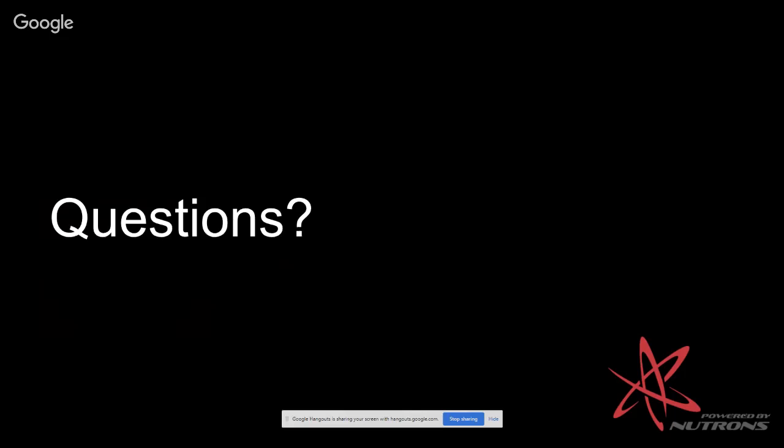So almost every single team will use some sort of gyro feedback in their code, because if you don't, you'll just drift off, and if you don't use encoders, you won't drive the same amount every time. So sensors become a very important part for repeatability of your autonomous routines. For teleop, they're not used as much, but you can use them.